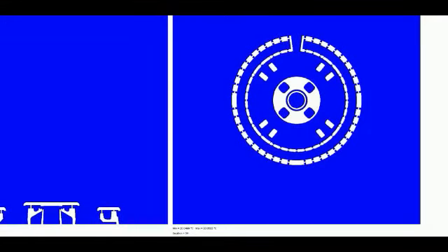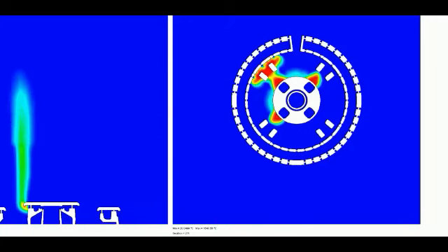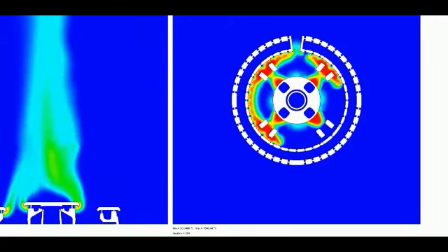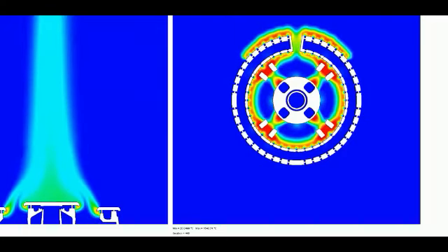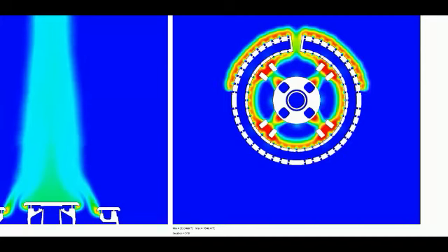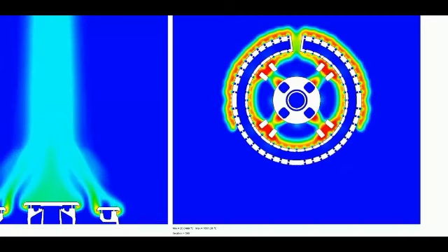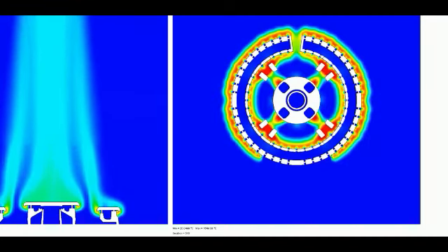During the actual solver execution, we can preview flow parameters to ensure sensible results. Here we're looking at the burner from two perspectives showing temperature. The initial heat source in the center can be seen and the flame propagating outwards from this transiently. The solution stops once the flame has become steady state.